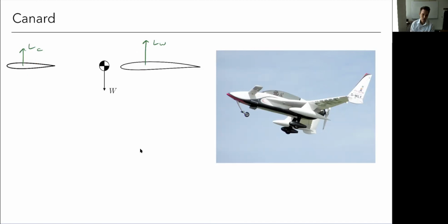We're going to have lower velocities on the wing, increased turbulence, a drop in lift generally in that region. And so that's going to create some increased drag. So even though the canard was carrying more lift and we needed less lift at the wing, because of that wake, it decreased some lift in the wing, and so we actually need to increase that back, so we kind of lost a lot of that benefit.